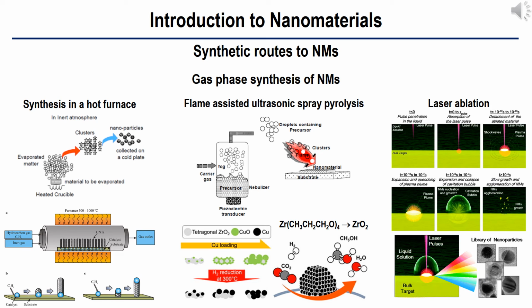The small dimensions of the particles and the possibility to form thick films make this method quite an efficient tool for the production of ceramic particles and coatings, and also an ablation source for analytical applications such as the coupling to inductively coupled plasma emission spectrometry.